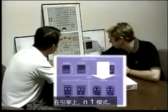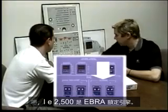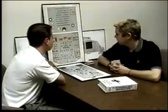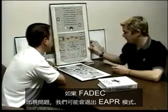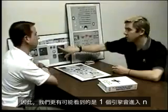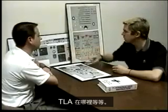On the engines, N1 mode. When might you select N1 mode, and what's our procedure? Well, the IAE V2500 is an EPR rated engine. So we run around in EPR rated mode all the time. It's possible for us to fall out of EPR mode if the FADEC has a problem. So what we would see is more than likely one engine would go into an N1 mode, either rated or unrated. And there are various indications down here that are going to tell us where the TLAs are and such.